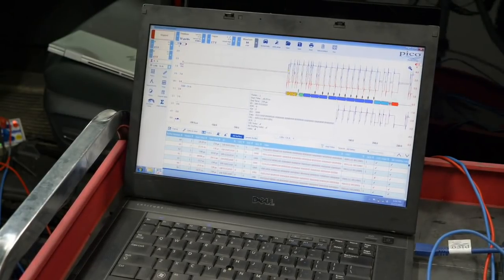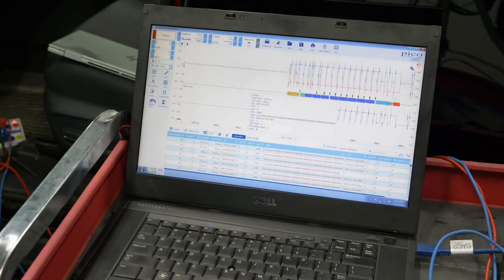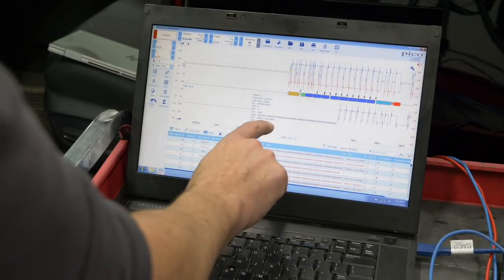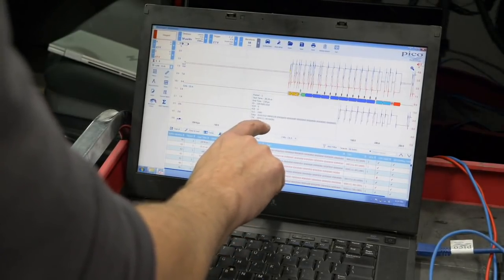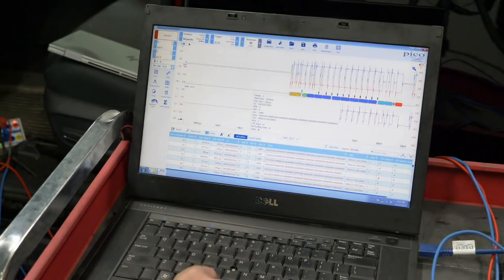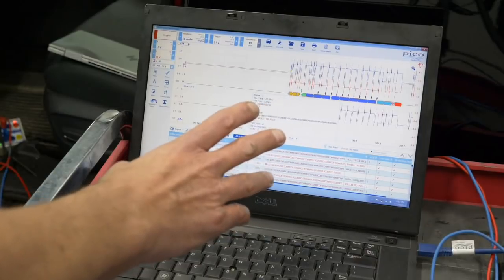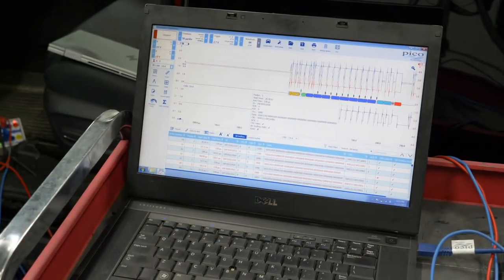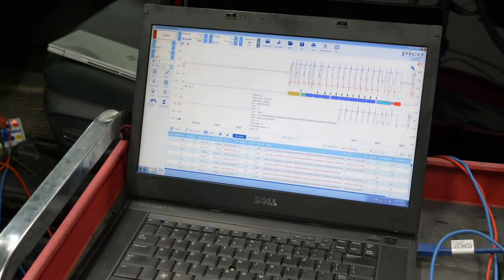It's just a way to do a sanity check to make sure this data really is what we thought it should be. Excellent. So if this CRC was not checked, that would be an indication that we have some kind of error that is not mathematically making sense. Yes. And that would help us to focus in from a diagnostic perspective.